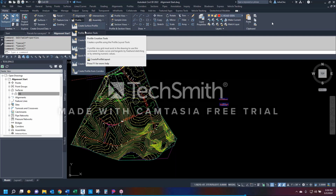You have to physically go grab it and move it, or go into the profile and edit the stationing to shift it over. Okay, don't expect it to slide left or right when you make your alignment stationing changes. Always make your alignment stationing changes before you profile, before you do everything that's profile related.